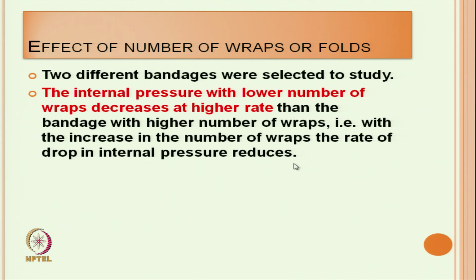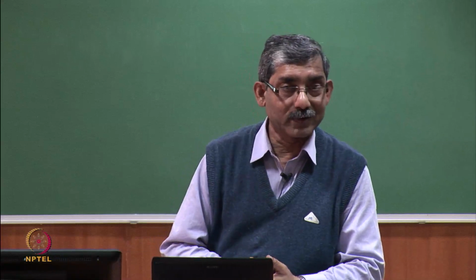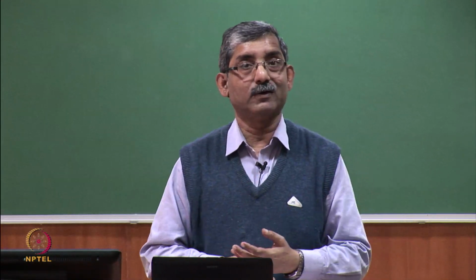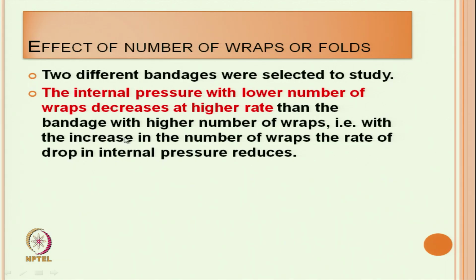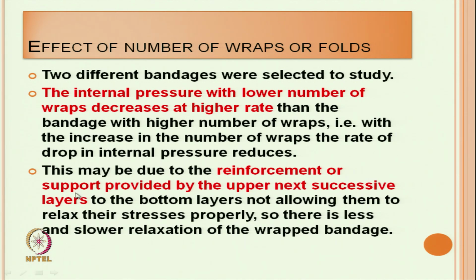So, that is why we have observed here, with the increase in number of wraps, the effect of drop in the internal pressure reduces. That means, if we increase the number of wraps, that pressure drop during time will reduce. So, if we want to retain the pressure, we must apply more number of wraps. This is mainly due to the reinforcement or support provided by the upper next layers of wraps.